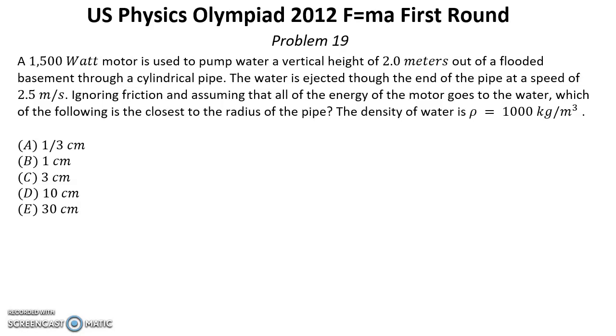Solution. We can calculate power by the regular formula. Power equals force multiplied by speed. In our case, force equals force of gravity, and this is how a column of 2 meters high moves up with a speed v equal to 2.5 meters per second. So we need to multiply the weight of this column by speed. That will be power.